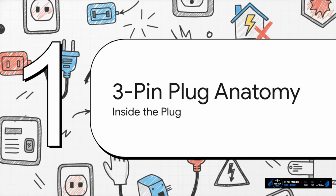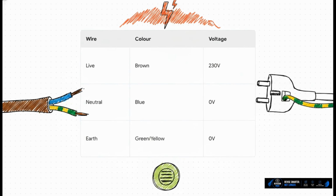Moving right along to Section 2, Anatomy of the 3-pin plug. Let's organize the chaos going on inside a standard UK plug. First up, we've got the live wire, which is always wrapped in brown insulation. This is the one bringing the highly dangerous 230 volts directly into the appliance. Next, we have the neutral wire, encased in blue plastic, and it sits at 0 volts. Finally, we have the earth wire, easily spotted by its green and yellow stripes, which also sits safely at 0 volts. Knowing these colors and their exact voltages is completely non-negotiable for understanding household circuitry.